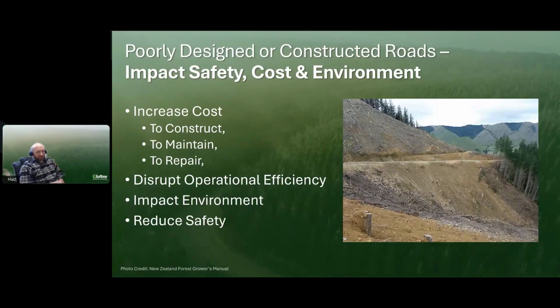From a construction standpoint, a pretty obvious one, and we talk about it lots, is choosing the road location to minimize earthworks. That is a big opportunity for reducing costs. If you put the road in a silly spot, it's going to cost more to build. From a maintenance standpoint, though, it could be something more subtle.